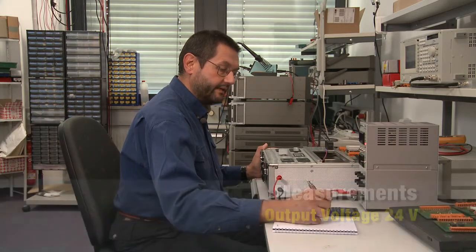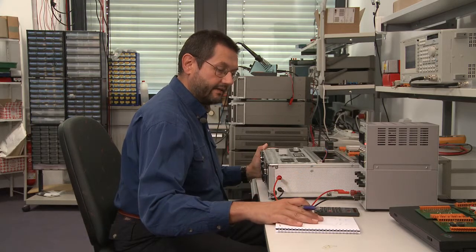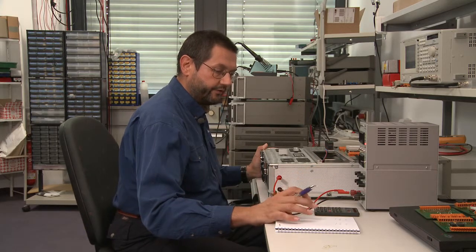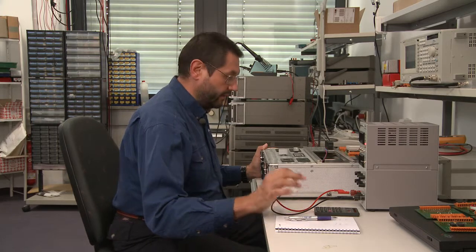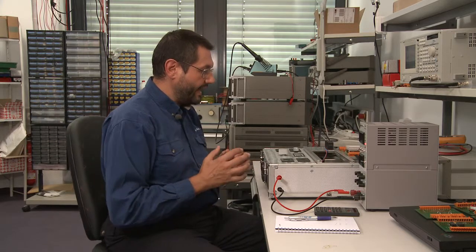So in this way we can easily calculate the input power and the output power and get our power difference, which is the power dissipated by the module. So at this point we can leave the system as it is and wait for a while until the conditions stabilize and the temperature increase will reach its final value. Then we can read the final temperature, and then we can calculate the thermal characteristics of the system.